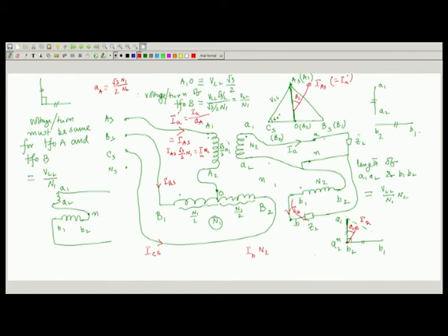currents will go in, but you see here there are two halves of this N 1, having the primary having total N 1 turns, of which N 1 by 2 turns is carrying I B S current entering through the dot. Therefore, this MMF must be equal to, let me write here only, so that you understand. So, this must be I B S into n 1 by 2, that is the thing.